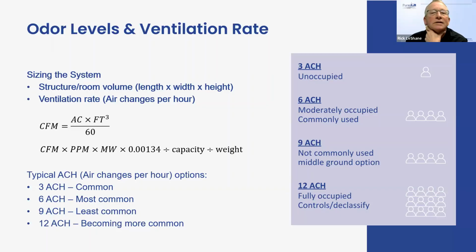All right. Let's see. Okay, so we need to know the volume of the room, the volume of the room the air is going to be pulled from, and the ventilation rate. So here's where we'll talk a little bit about that. There are different air change rates to keep in consideration when sizing a system. You can see some examples of them right here.